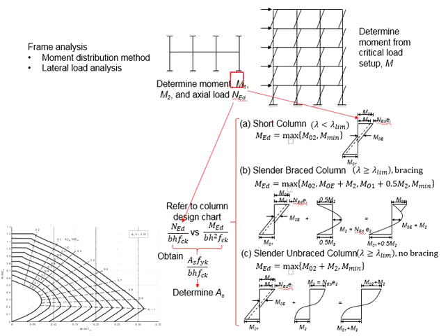However, the moment that you obtain, you cannot use directly as the design moment, since there will be other factors governing the design moment. You will need to consider those factors in order to conclude the design moment before you can determine the area of the reinforcement.